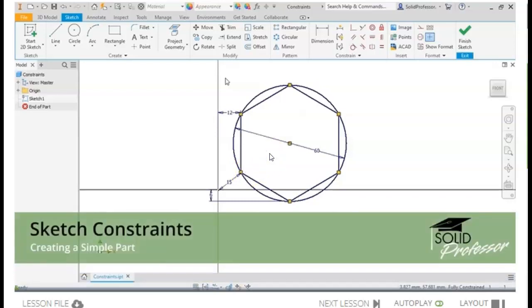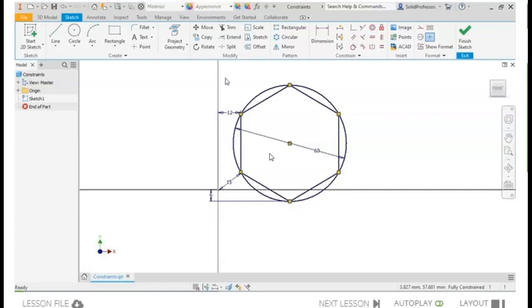Constraints are geometric relationships that you can use to relate sketch segments, model geometry, and the center point or origin of a sketch. Constraints are key to parametric modeling since they can be used to constrain sketches alongside dimensions but are more flexible to updates.